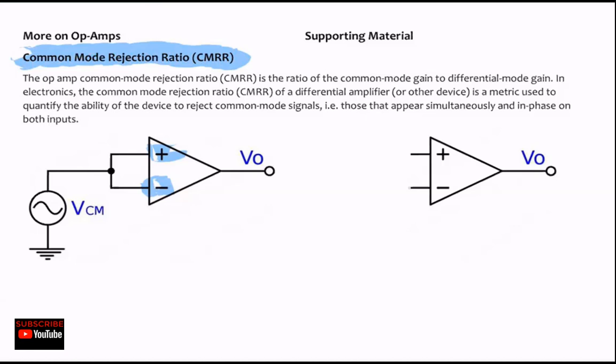So common mode rejection ratio, also referred to as CMRR, basically exists in the differential amplifier that we did last week. When you have a PCB board and a circuit on it, it is operated in a high electromagnetic field. In that case, the electromagnetic interference, which is coupled to the circuit, is also common to both terminals. Okay, so this is one common source of the common mode input signal.